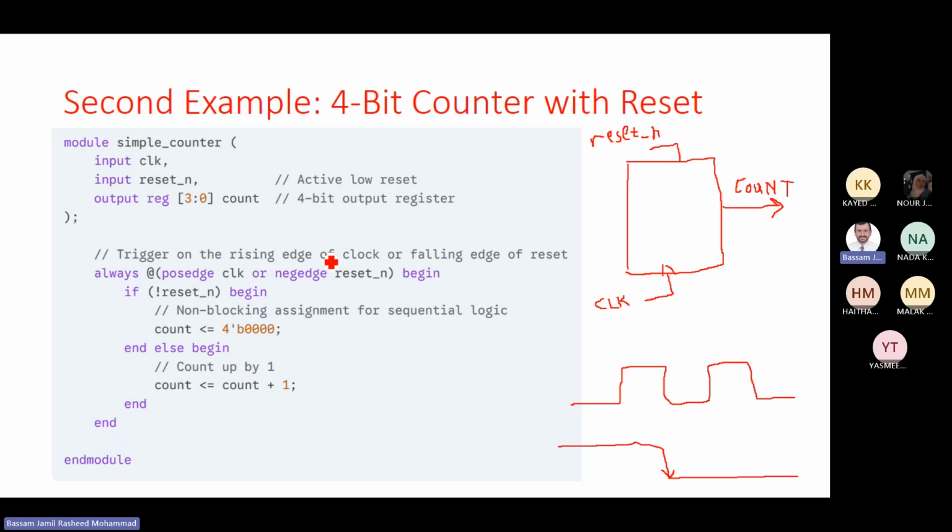Those control circuits are implemented by what? Sequential circuits. What's inside them? Flip-flops and some combinational logic. When you power up, the flip-flops come up with what? Random values. We learned about this feedback inside a flip-flop design. So that's interesting. We power up our device and it comes up in a random state. That's a very scary thought, right? So to prevent the hardware from powering up to a random state, what do we do?